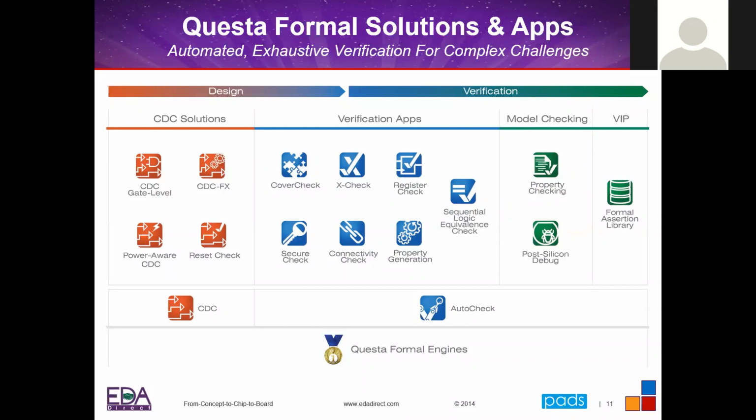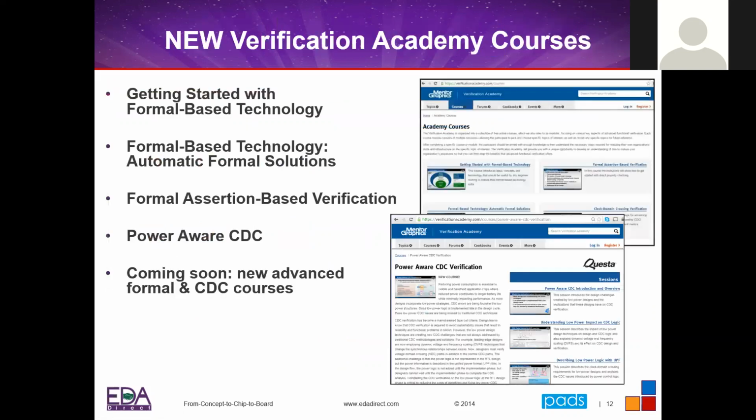So it's kind of a much better tool. I know Xilinx and Altera do have some CDC analysis things just in the tools, but they're going to give you a lot of false positives and false negatives. So it's going to say that there are errors that are maybe not really errors, and it's probably going to miss some things that are actual CDC errors that you won't find. And so that's kind of what the CDC tool is all about. We'll talk about Autocheck and CDC in more depth.